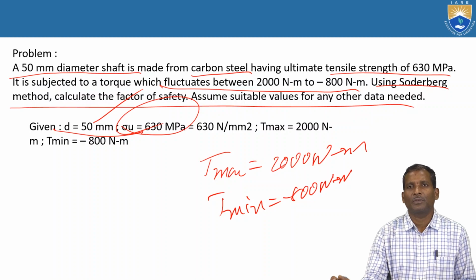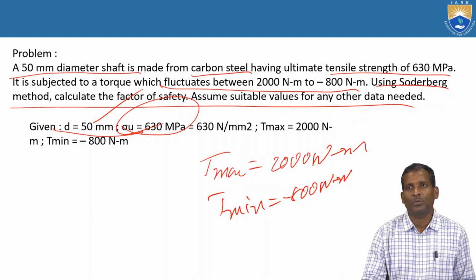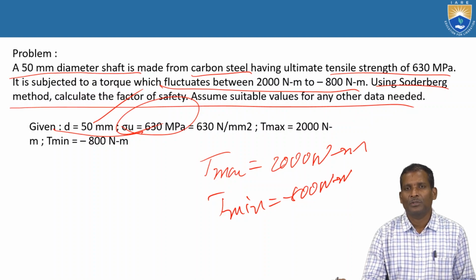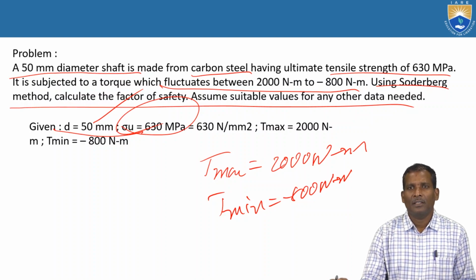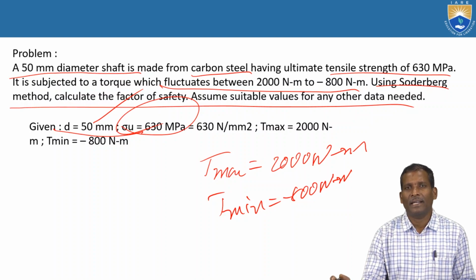It is clearly given that we use the Soderberg method, which is useful for ductile materials. We calculate the factor of safety and assume suitable values for any other data required.